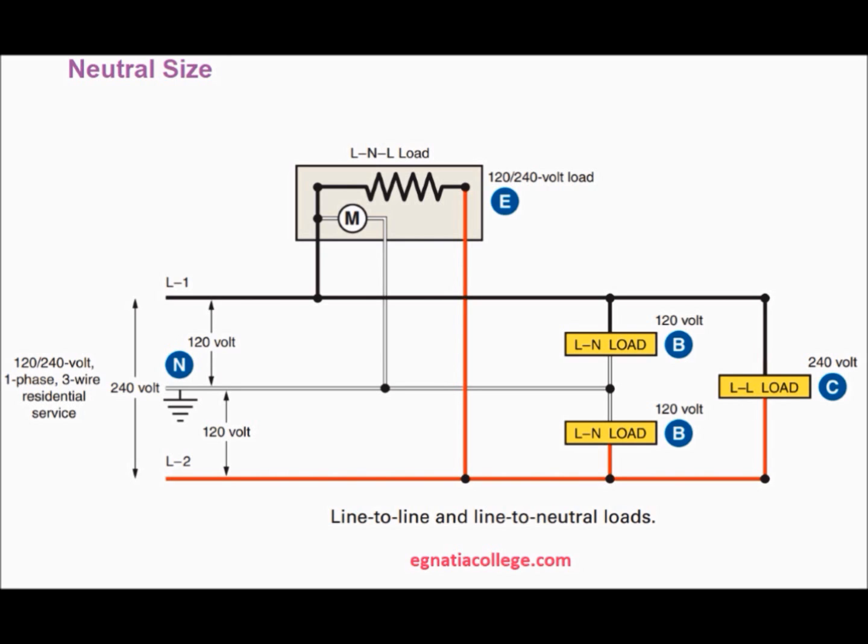The neutral conductor shall have sufficient ampacity to carry the unbalanced load. And the maximum unbalanced load shall be the maximum connected load between the neutral and any one ungrounded conductor. In this residence, a number of loads carry little or no neutral current, including the electric water heater, electric clothes dryer, electric oven and range, electric furnace, and electric air conditioner. Thus, we find logic in the CEC, which permits reducing the neutral size on services, feeders, and branch circuits where the computations prove that the neutral will be carrying less current than the hot phase conductors.